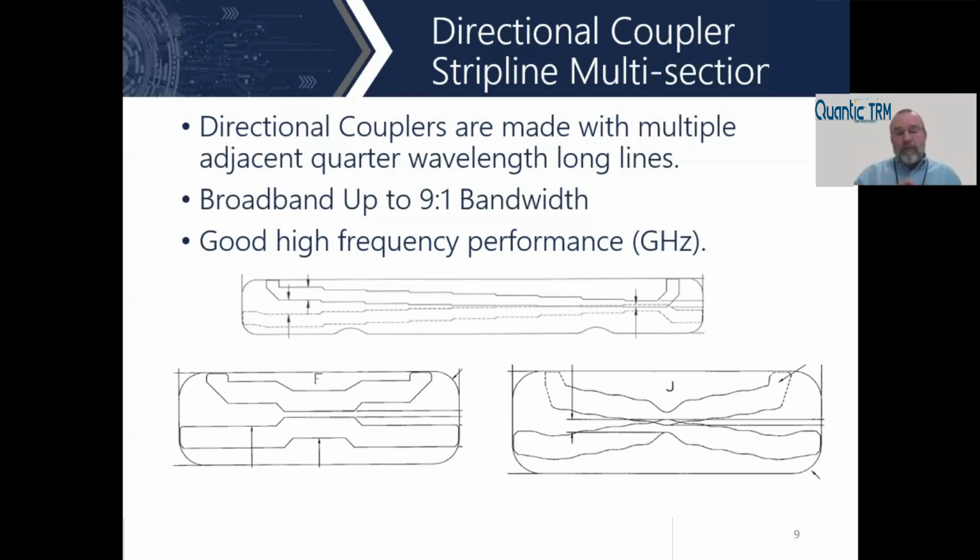For example, on the top here, the longer tapered asymmetrical taper on this one over here has roughly a 9-to-1 bandwidth. That one there is one way of realizing this. Another way of doing this is using a symmetrical taper. The one in the lower right, for example, also has a 9-to-1 bandwidth, but that is a symmetrical taper with a smoothing function between the individual sections, as opposed to the one on the top, which actually uses an almost digital type of step function in there.